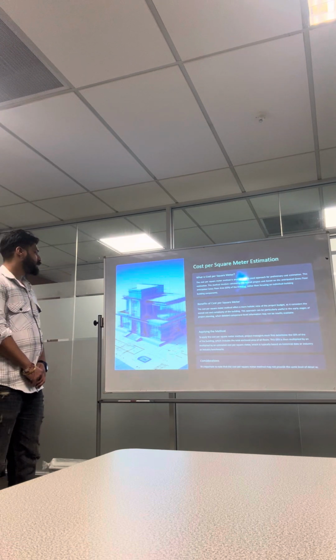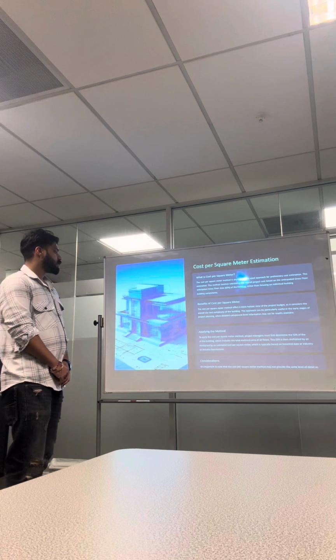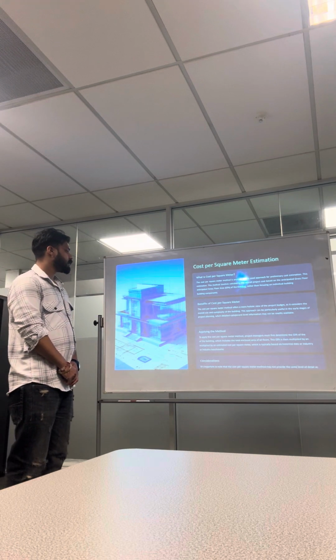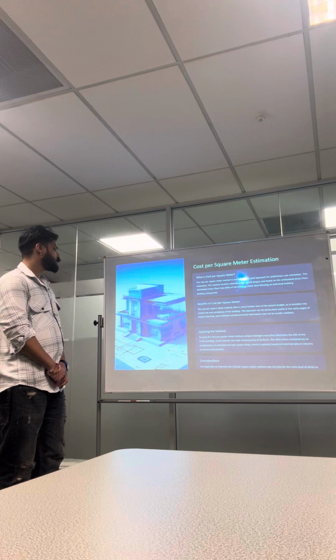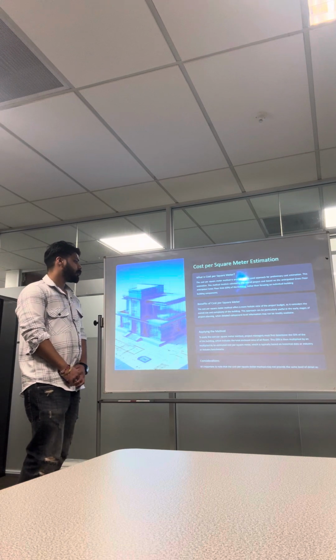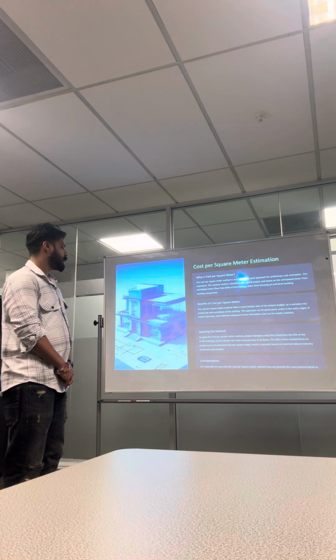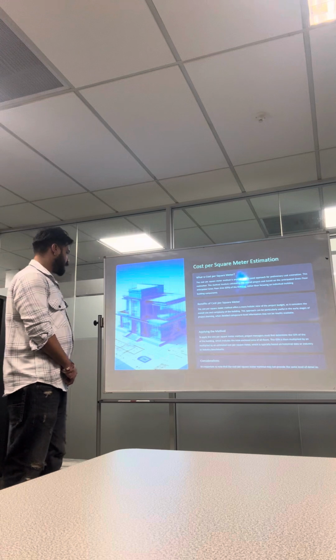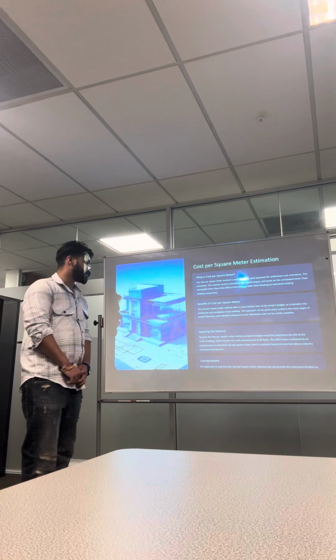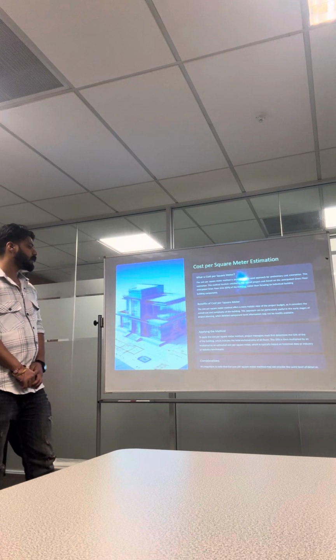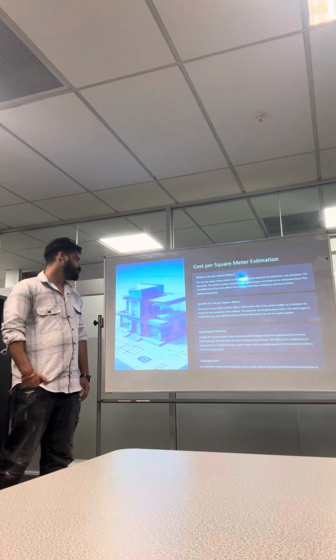Applying the method. To apply the cost per square meter, project managers must determine the GFA of the building, which includes the total enclosed area of floors. The GFA is then multiplied by an estimated cost per square meter, which is typically based on historical data or industry benchmarks.